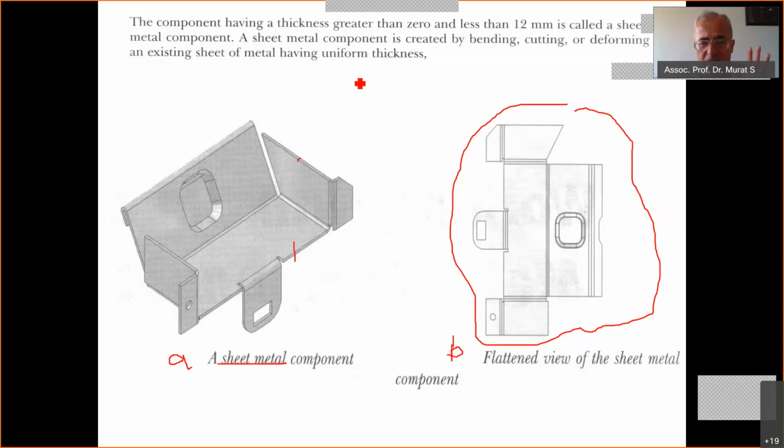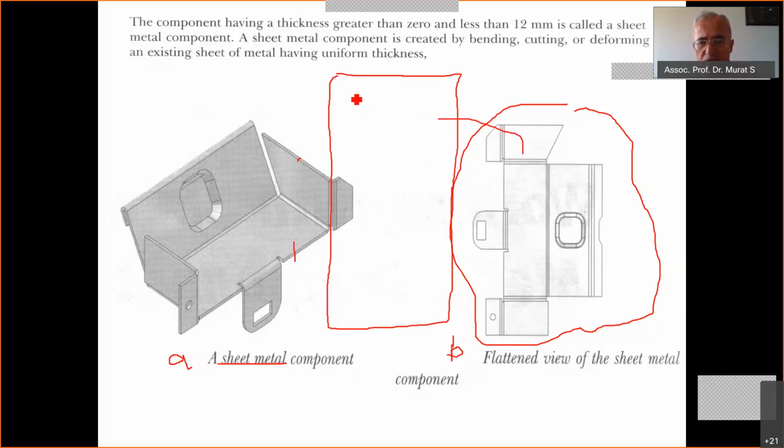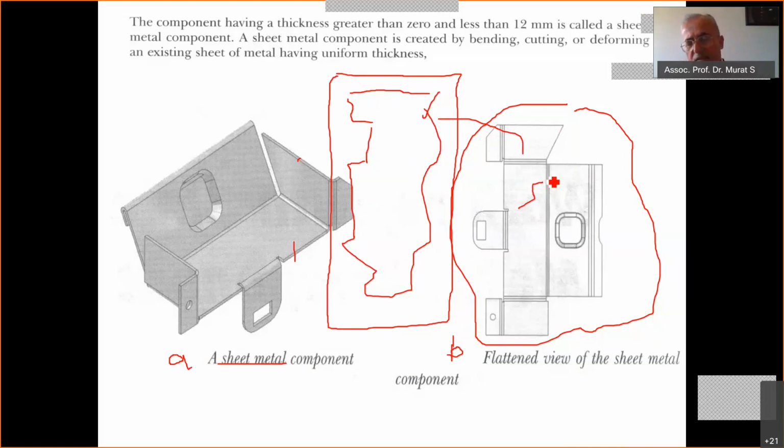We find at the beginning, of course, from the stock, depending on the main geometry of the object, in most cases a sheet in rectangular prismatic shape. Then we take a rectangular prismatic sheet and give the boundaries in size and shape through this figure, using special pens or directly using some welding robots. This projection shows a sheet metal work as unfolded, flattened over a plane. It's called development.